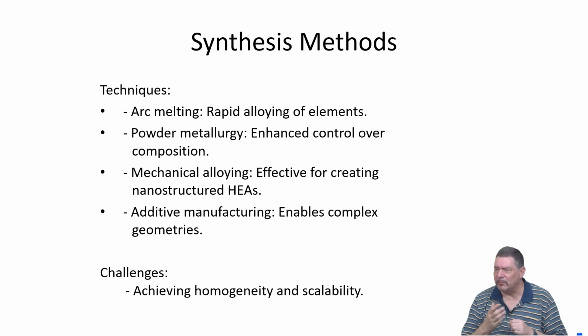So either one does post-synthesis annealing treatments and deformation annealing, this is even better. But many people go for powder metallurgy routes because it is easier to control not only the composition but also the composition of the forming phases. Especially for very high melting materials, that's also the more prominent route in terms of cost efficiency.